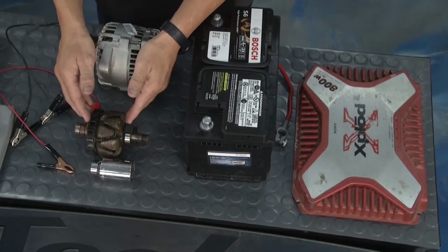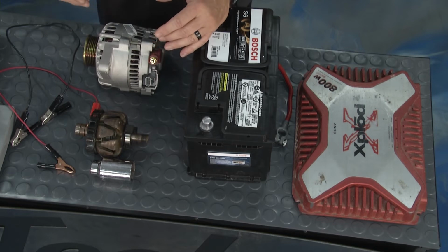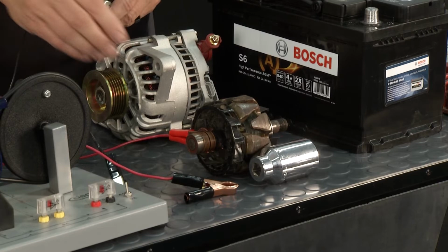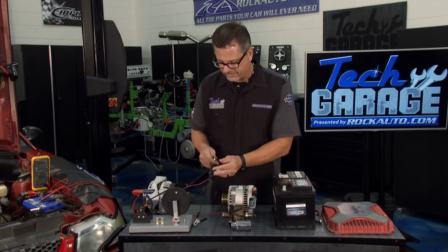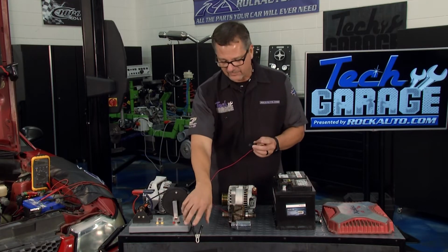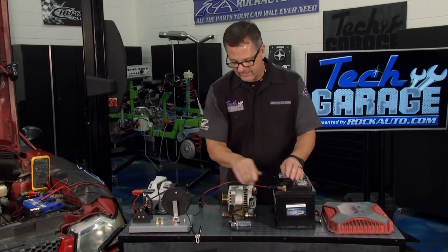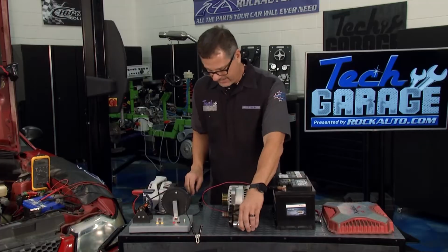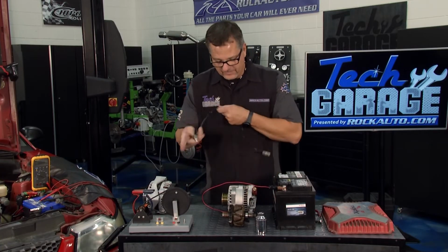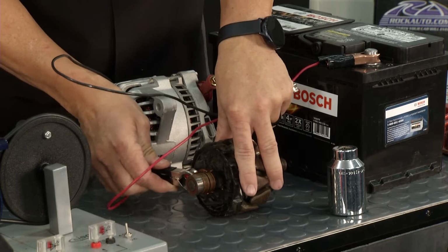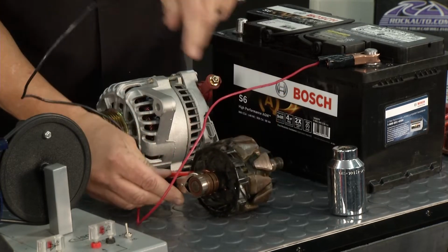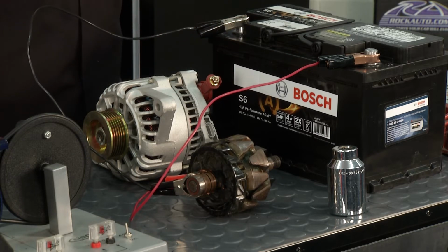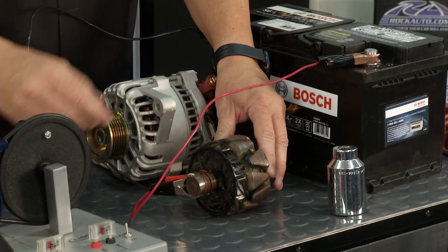You can see a rotor assembly right here, and I can actually magnetize it for you. This is really cool. I got a positive cable right there, and these are the actual slip brushes inside your alternator that it would connect to. I'm going to connect the positive cable to the battery. And then I'm going to go out of this big magnet here with these claw poles, and connect the negative battery cable. I'm going to take the negative battery cable and slide it on the other ring, making sure they're not touching. That wouldn't be a good thing. And then I'm going to connect it to the battery. So right now I created a ginormous electromagnet.